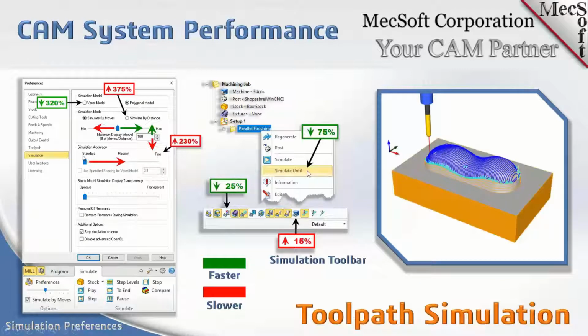And then the simulation accuracy. If you're using the voxel model, you can enter the volume size, as Joe mentioned, which will affect the simulation time. But you can also, go ahead. Sorry, Don. Just wanted to correct that. It's not the volume size. It's really the spacing between each of the pixels that you're affecting there. Oh, okay. So the denser or tighter the spacing, the more accurate your representation.